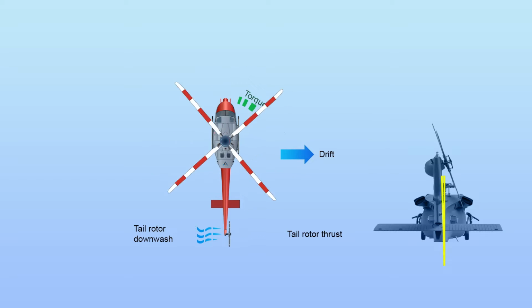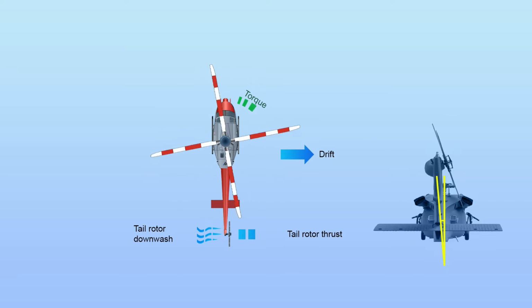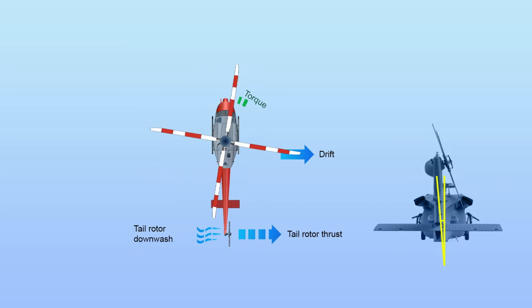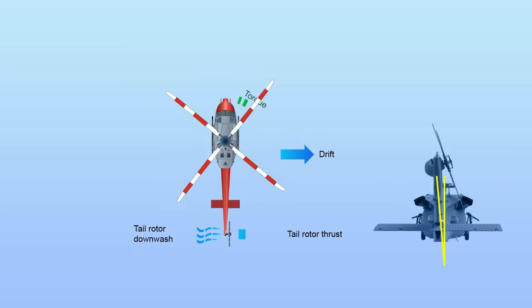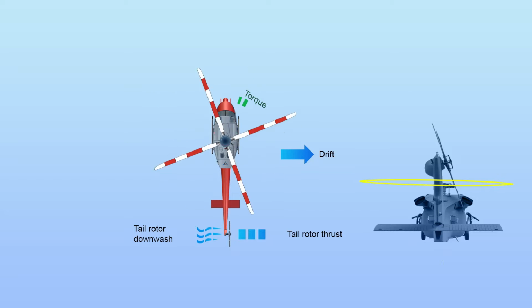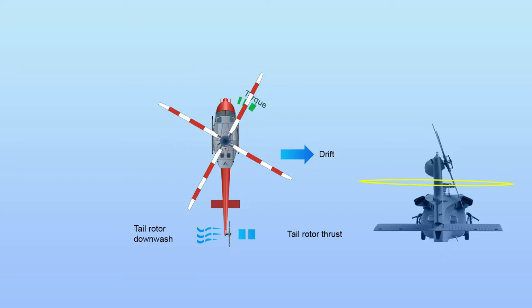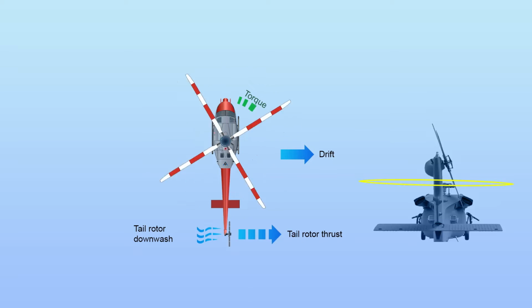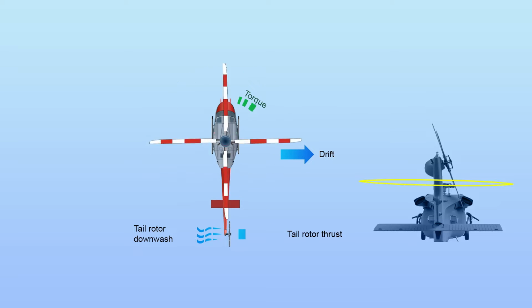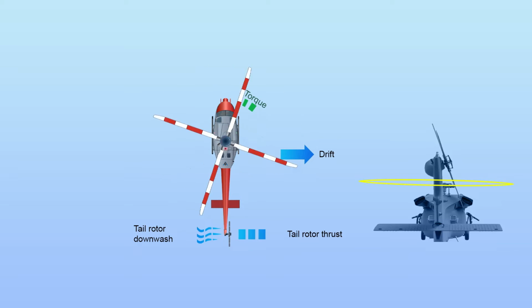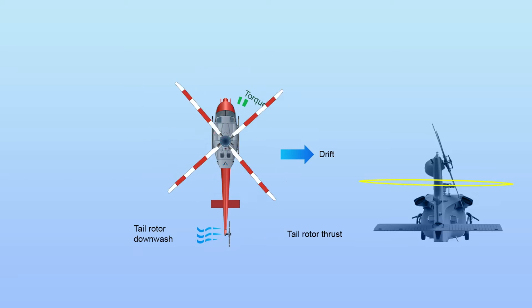The main transmission is mounted at a slight angle to the left, when viewed from behind, so that the rotor mast has a built-in tilt to oppose the tail rotor thrust. Flight controls can be rigged so that the rotor disc is tilted to the right slightly when the cyclic is centered. Whichever method is used, the tip path plane is tilted slightly to the left in the hover.